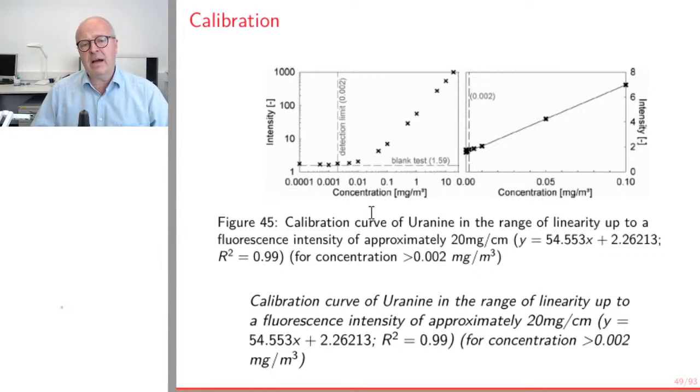And at very high concentrations, it will not be linear either, but we all hope that you will never have a sample with that concentration, because it would mean that your calculation of tracer mass has been wrong and failed, and you have just polluted a river and made it look yellow or red, which nobody wants.